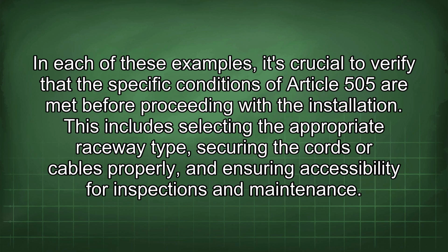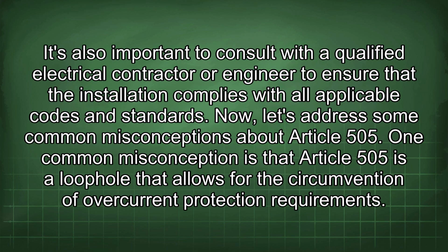with the installation. This includes selecting the appropriate raceway type, securing the cords or cables properly, and ensuring accessibility for inspections and maintenance. It's also important to consult with a qualified electrical contractor or engineer to ensure that the installation complies with all applicable codes and standards.